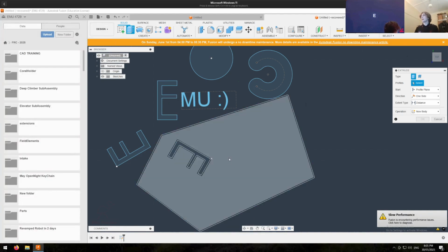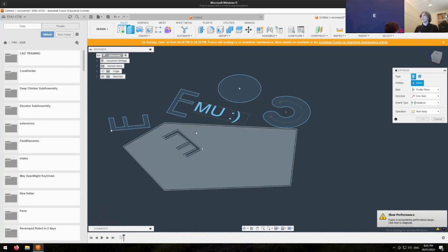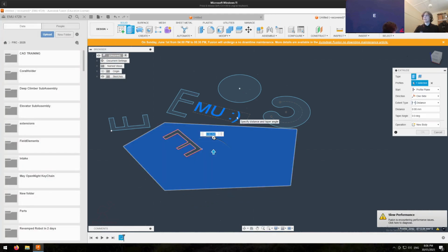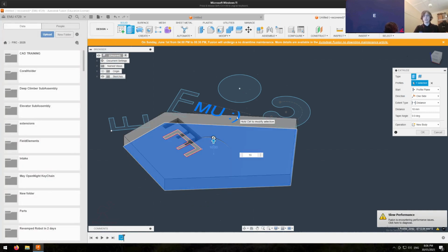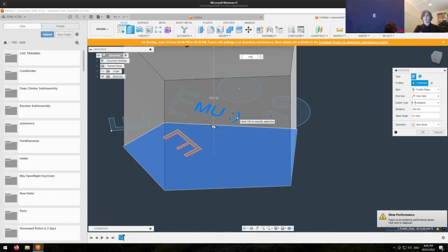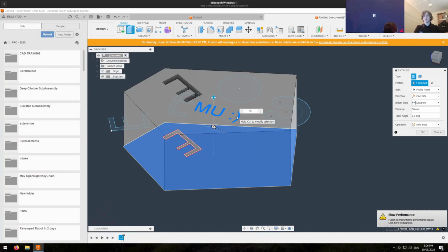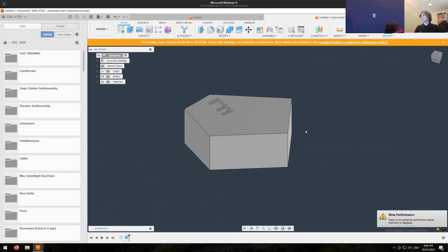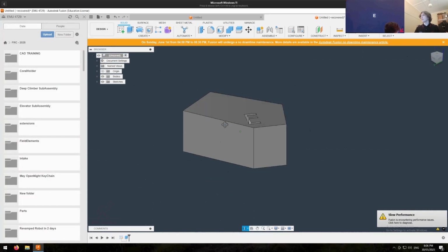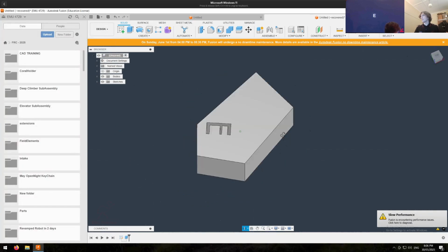What this tool does is you can select an area. I just clicked on that. And then you can type in a number, let's say 10, and it will extrude it out. And put in like 50. And wow, look at that. So I've made this little block now.